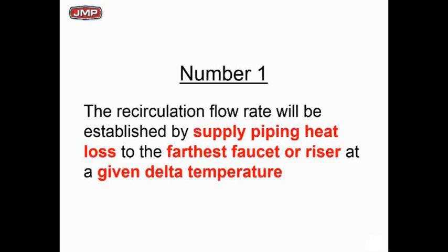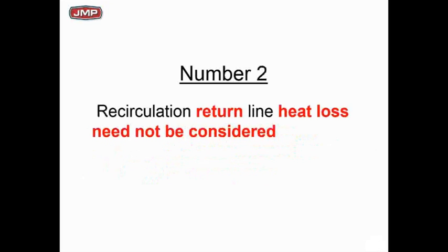How close? We're going to use 10 degrees a day, but you might use 20 in your designs or 5. It does not matter. The point is we're trying to make sure there's hot water available when you need it at the end of the pipe.